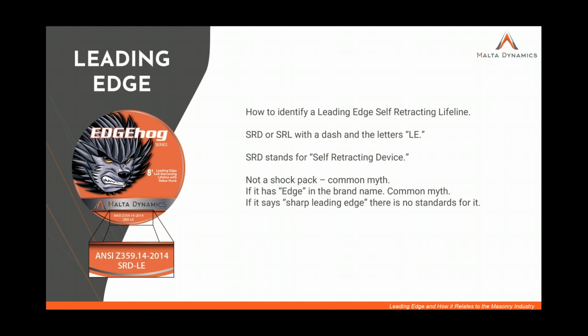There are some companies out there that will put edge in the name of the product. That does not necessarily mean it's been tested for leading edge. And then the other thing I'll remind you of, if it says sharp leading edge, you need to know there are no standards for sharp leading edge testing as of yet. And SRD, if that's new to some of you, and I know it always is, that stands for self-retracting device, which is just another way of saying self-retracting lifeline.